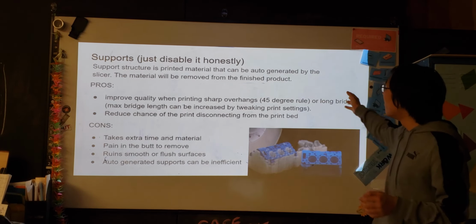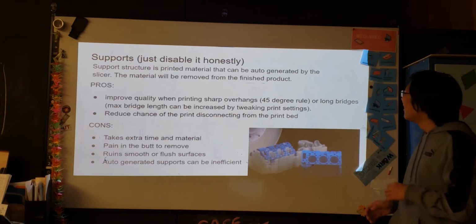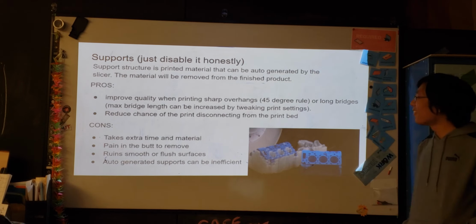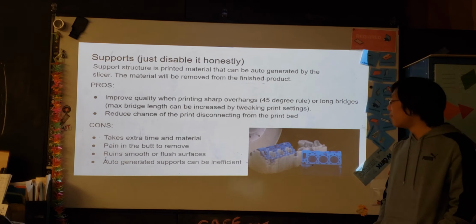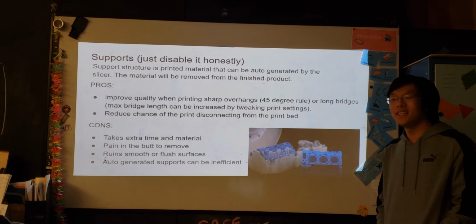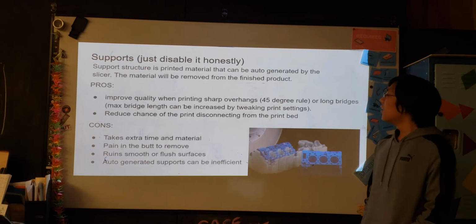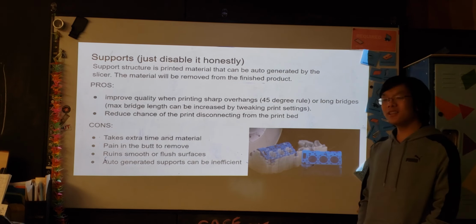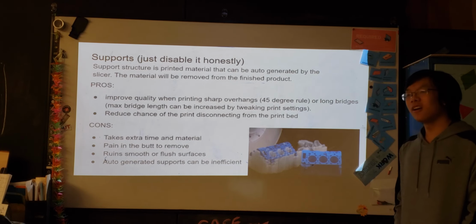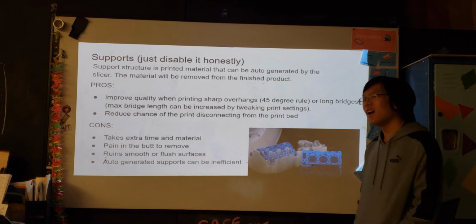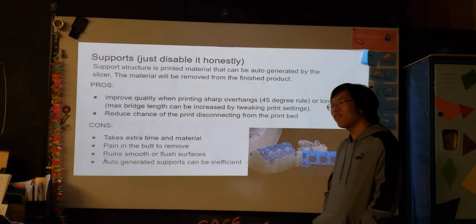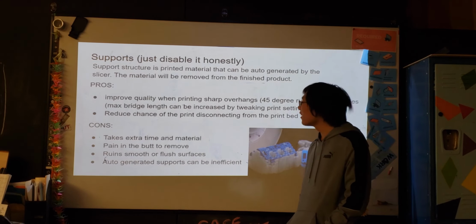Okay, here we go. Supports. Just disable them. With the stuff we're printing, you don't really need supports. We're not going to be printing extremely fancy geometry. If you need to enable supports, you can, but you honestly just want to go without them because they take up a lot of time. The supports taking up material doesn't really matter for us, but the time really does matter.